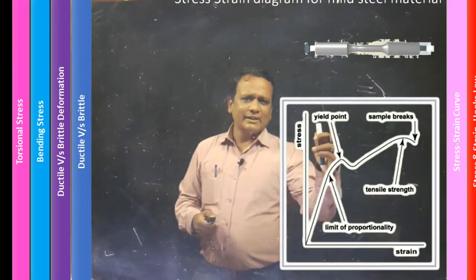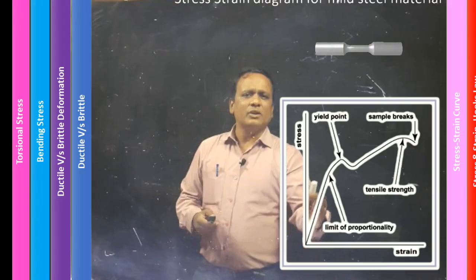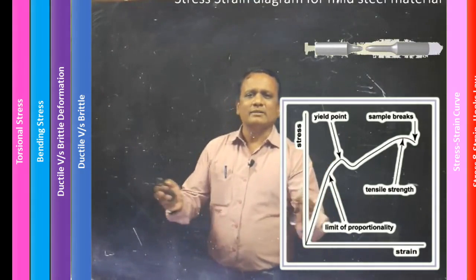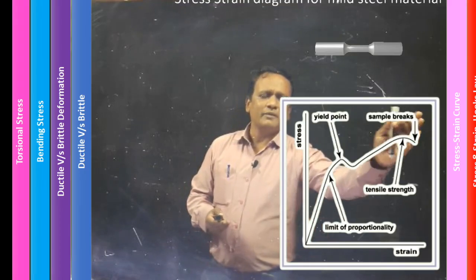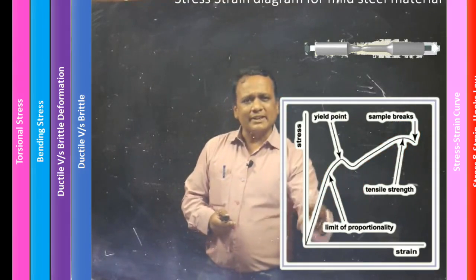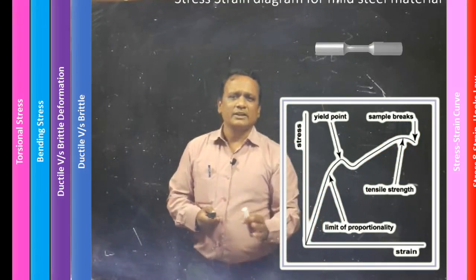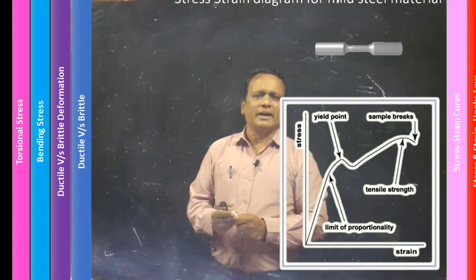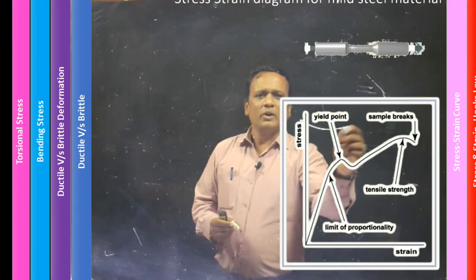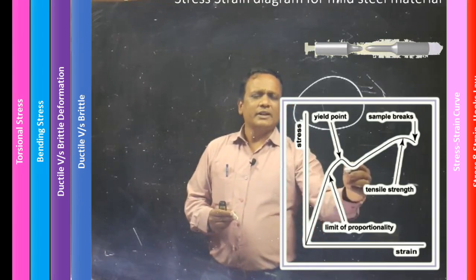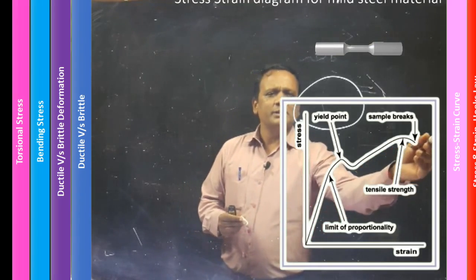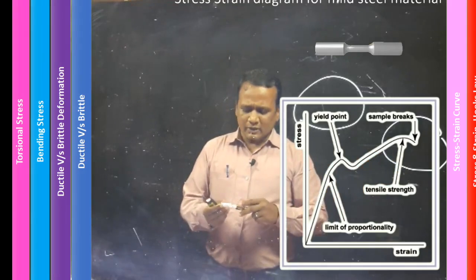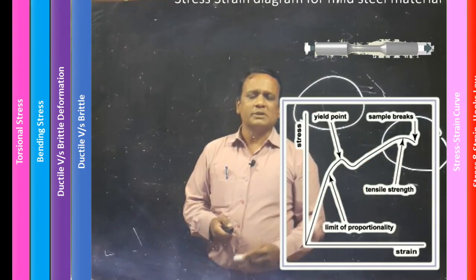I can see here that as the load is applied, there is a linear increase of stress and strain. This part of the graph we call the elastic region. The rest of the graph we call the plastic region. In the elastic region, the stress is directly proportional to the strain, which refers to Hooke's law. Once it moves above the elastic region, what you see here is the yield stress. Further, it enters the plastic region, and at the end the specimen breaks at this point. That point would be the ultimate strength of this material, as you see for a dog bone specimen under tensile load.